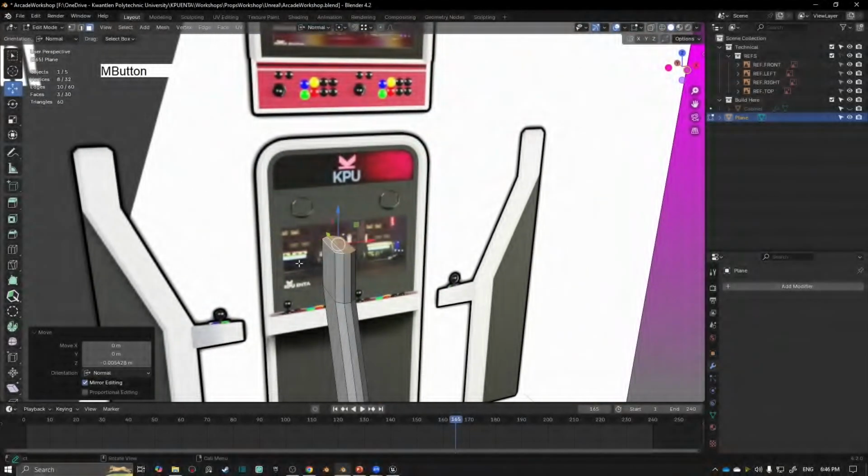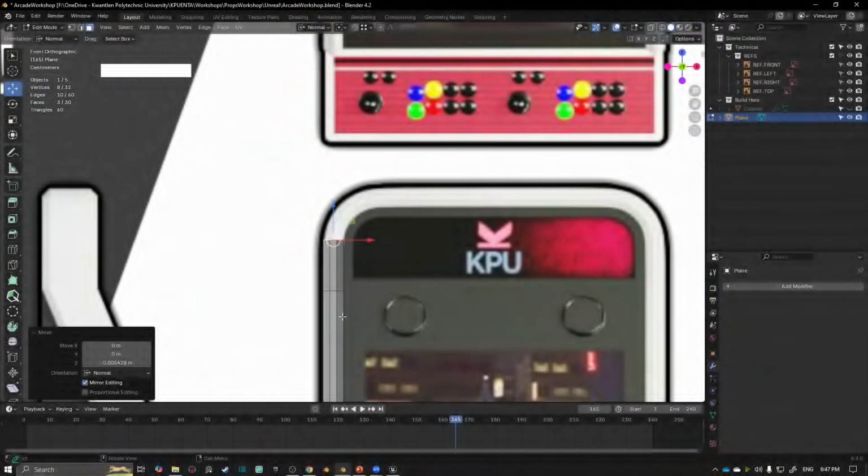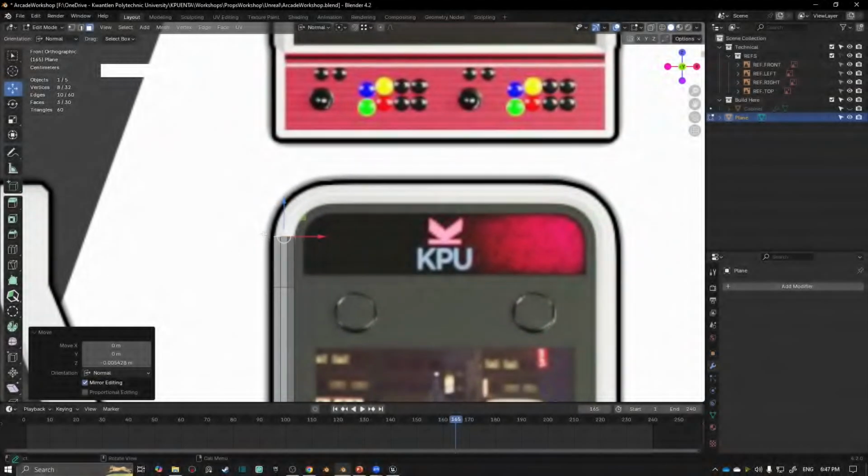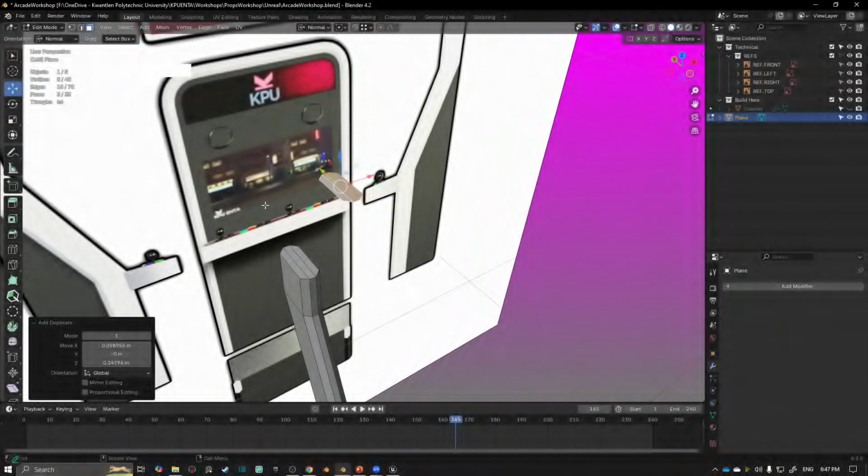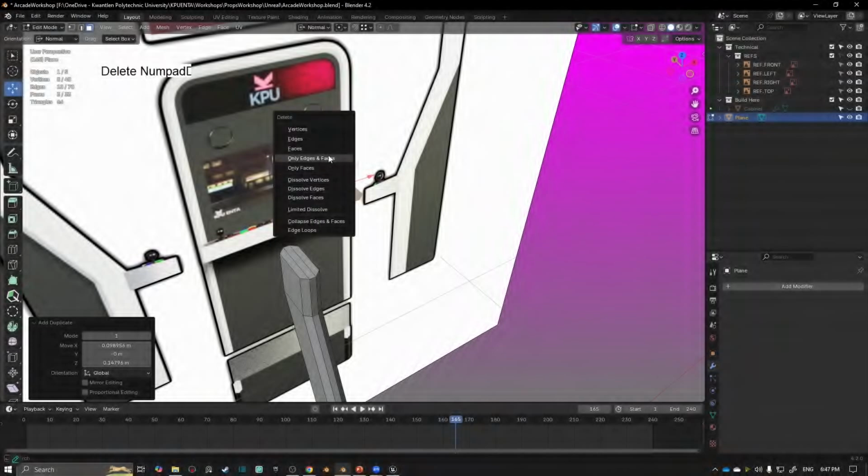What I'm going to do is duplicate these faces, move them up, extrude them across, and then we're going to connect everything after. So I'm going to go into my front view. I'm going to hit Shift and D to duplicate, and that will rip those faces off and duplicate them. So you should see I've got my copy up here.